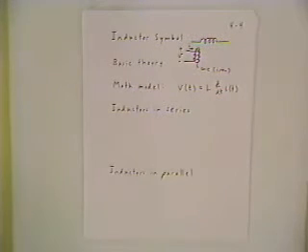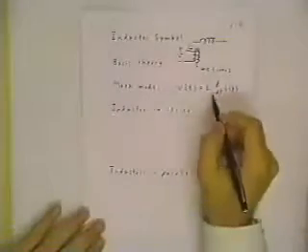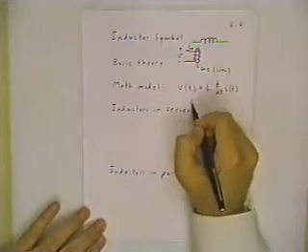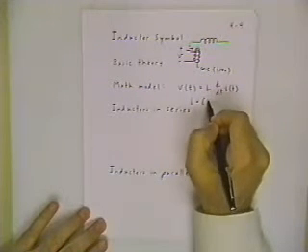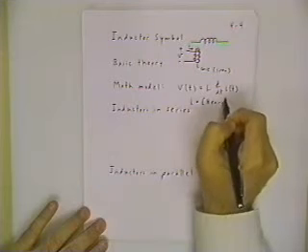Frankly, I find it much easier to understand and discuss capacitors with you. So the thing to do is understand the basic theory of the parallel plate capacitor to help you remember that linear model, that the capacitor current I is C dV/dt. And then once you've figured out and remembered the capacitor model, all you have to do is remember that the inductor is the companion component, and you just reverse the roles of V and I. You replace the capacitance with the inductance, and that's all there is to it. For an inductor, you have an element parameter called the inductance, L, in henries.